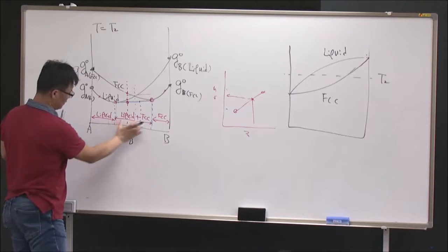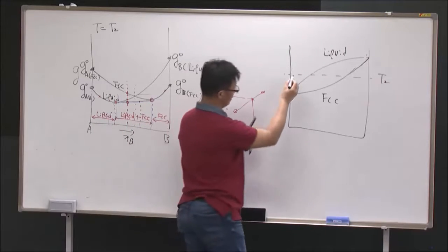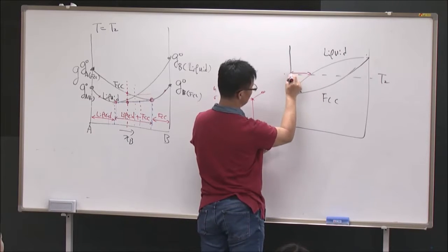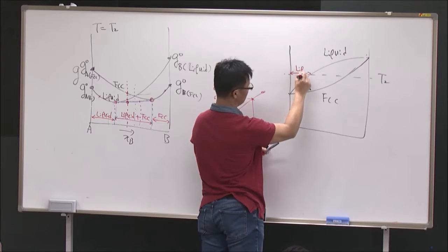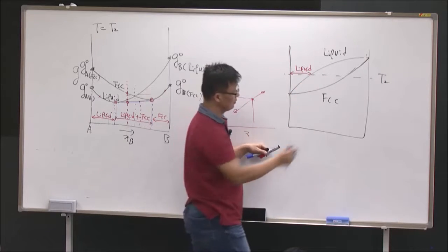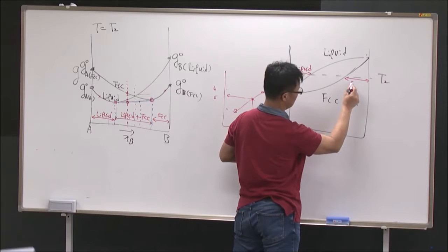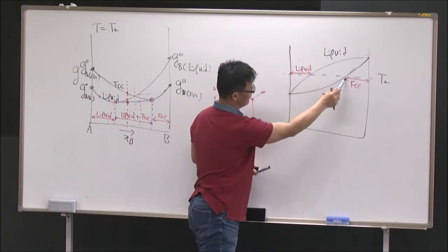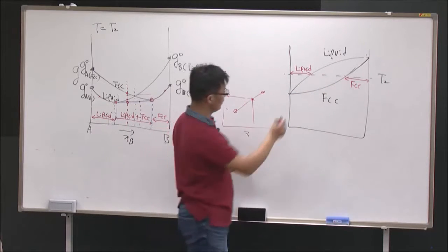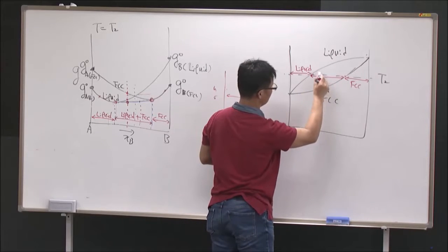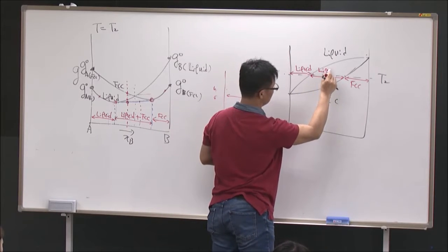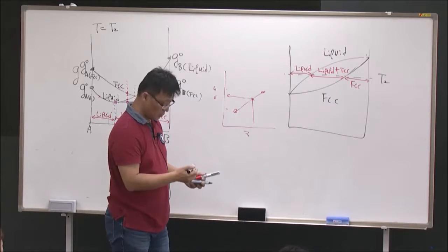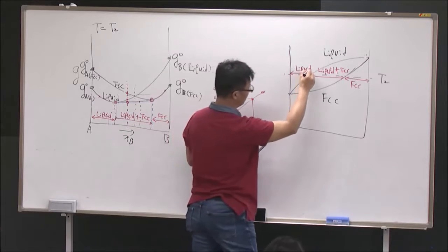Now if I connect this one with this one, at this temperature, up to here, I have liquid phase. Am I right? Here, I have FCC phase. In the middle here, I have the two-phase region: liquid and FCC phase. Now, when you look at this, you have to be very careful.